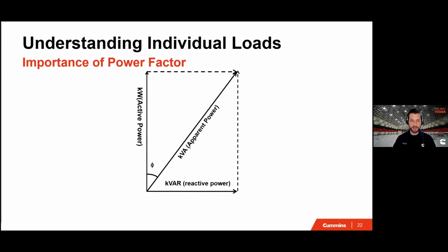Now that we've covered the big early decisions and the high level overview of general sizing in the most general sense of the word, now let's start talking about individual loads. So to kick things off, we're going to have a good old review of the importance of power factor. Power factor is the ratio of real power, measured in watts, versus the apparent power, measured in volt amps. Breaking down the individual legs of this alternating current power triangle I have shown here.